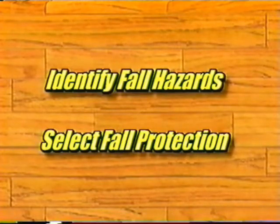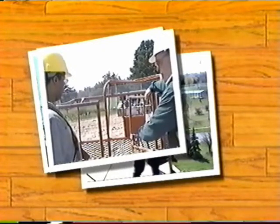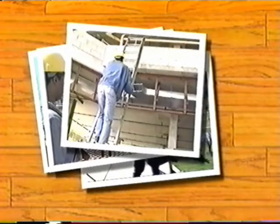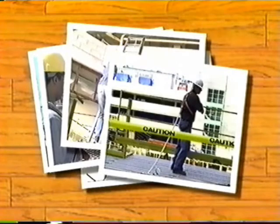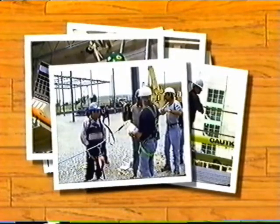The first step in eliminating fall-related accidents is to identify specific fall hazards in your work area, then select fall protection methods to deal with them. Solutions may include changing work procedures to eliminate the hazard, installing guardrails to put a barrier between you and the fall hazard, safe use of a powered elevating work platform or properly built scaffolding, using a ladder that is properly set up and when three-point contact is maintained, using a travel restraint system to keep you back from the fall hazard area, or a fall arrest system to stop a fall in progress. Whatever the solution, you must know how to use the equipment correctly and maintain it carefully.